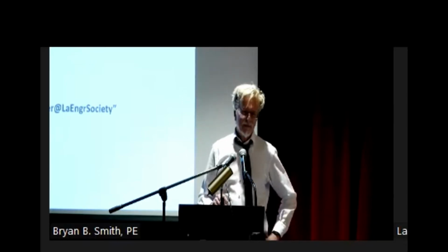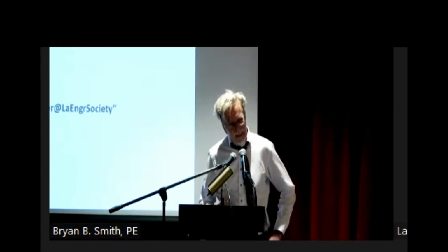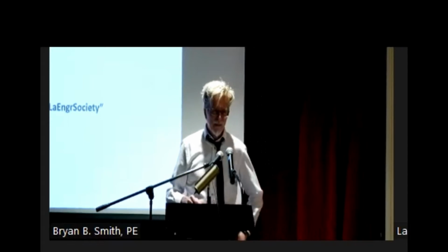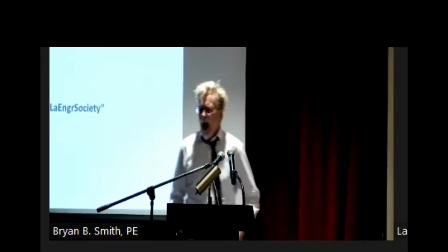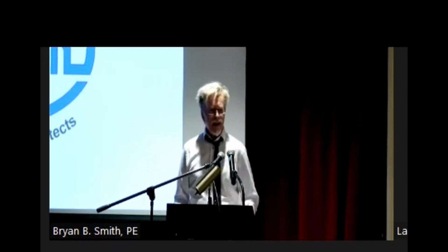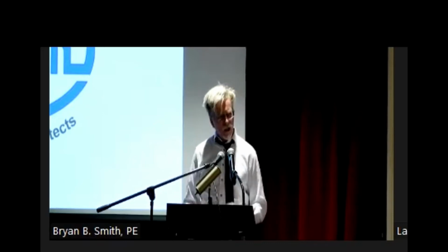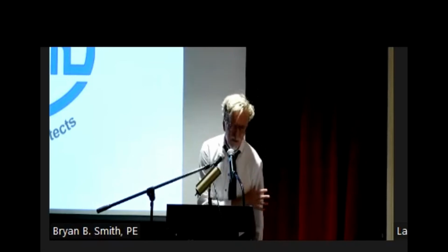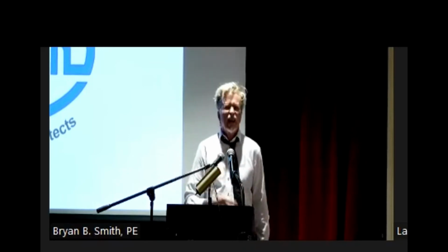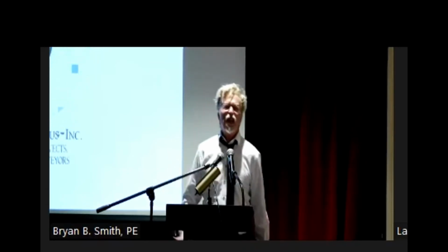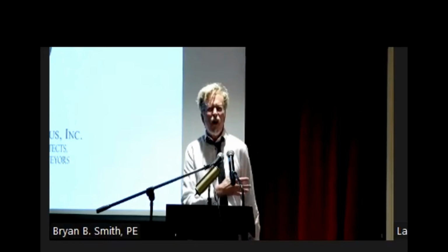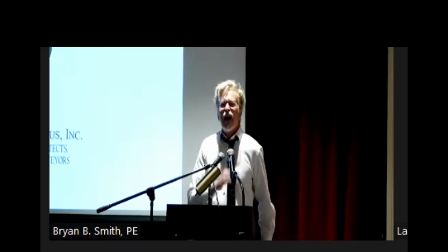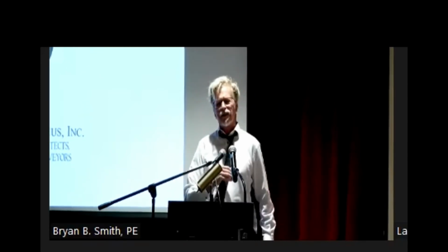Check valve. Check valve was a little slow. So the check valve's like, I'm trying to close, right? This wave is hitting me and I'm trying to close. And it lets some water by. In this case, it's wastewater. But, you know, water sounds better because we just ate dinner. It's getting a little flow by it. Oh, I'm going to close. It's good, right? And then I'm going to finally go closed.